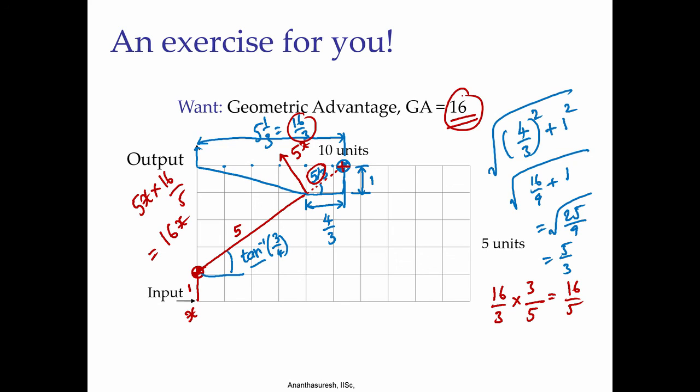Now, let us complete the linkage by using a different color. So, we can choose any point here and fix it, the direction is important, and join this point to that, okay. And again we have to choose some point here, fix it like that, and now this should be rigid, this should be rigid, and then we are joining this to that. So, that should be rigid as well, that is the coupler body here, and then we will fix this anywhere, it does not matter where you fix it, that is our mechanism here.